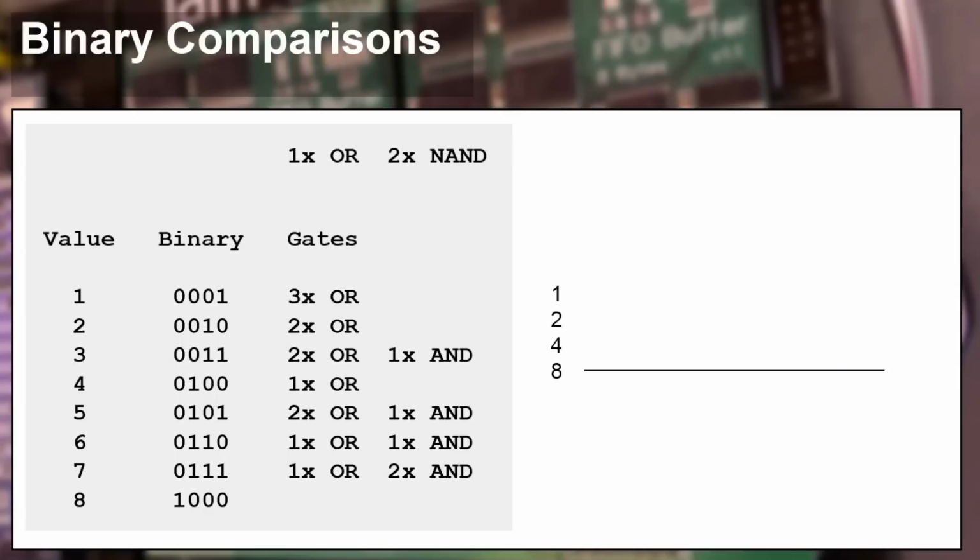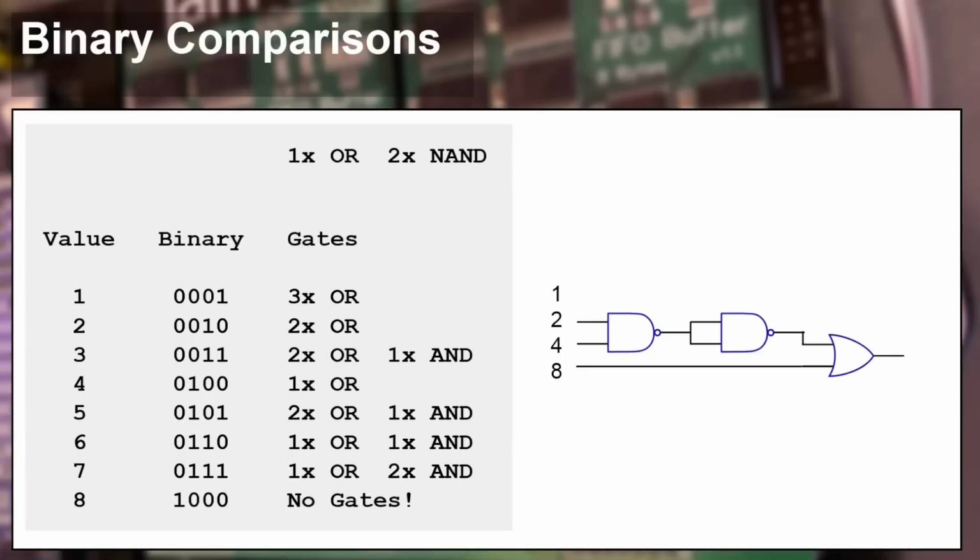There's 7, and 8 is of course the simplest of all, but we tried it and it didn't work. So if the 2 we can actually do trivially, 1 doesn't work and the average is not very desirable. But while we don't have the exact gate matches for this, we can create an AND gate using the 2 NAND gates. So this circuit is going to tell the sender to stop sending once we hit 6 bytes in the incoming FIFO buffer, and I think that should give enough time for the sender to stop before we go past 8 bytes. Let's see if we can hack that into the existing circuit.